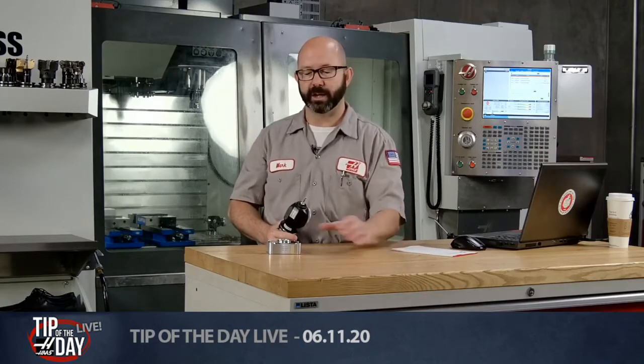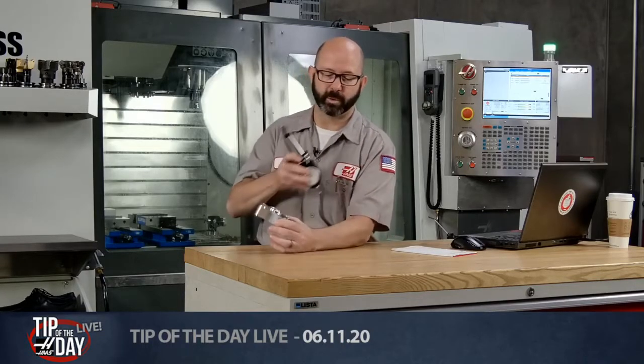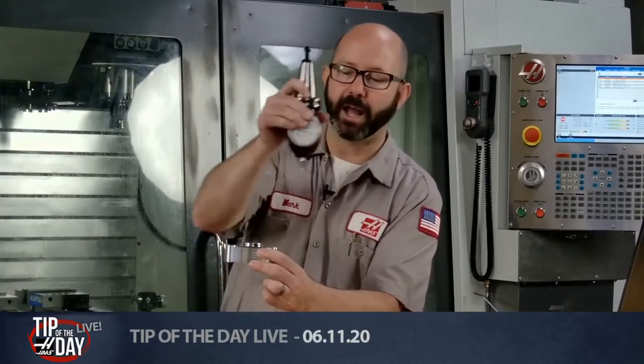Once you've set that position for all of your tools, then every time you add another part that's at a different location than where you touched off those tools, you need to measure the distance. So we would measure the distance between where I touched off the tools and where I'm now going to run my tools. If this is my G54 and my G54 top of part is 2 inches higher in the Z than where I touched off my tools, then we'll just take one of those tools, touch it off here, look on the screen, see that it's 2 inches higher, and that will be my new work offset if you're touching off manually. So my G54 Z value will now be 2 inches.